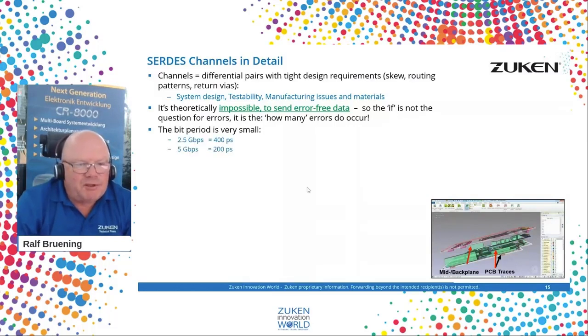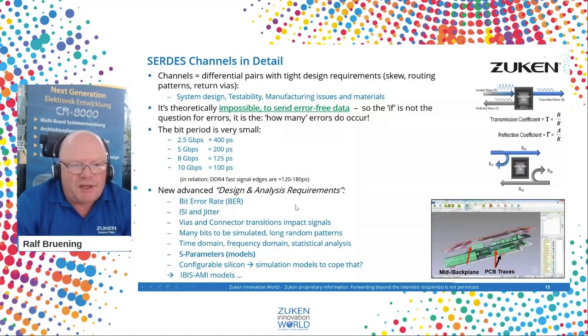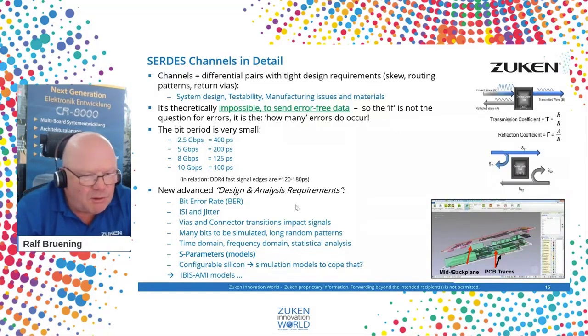The bit periods are pretty small. So depending on the data rates, we have very tiny bit periods, even faster than fast double data rate memories. As mentioned, we have the S parameters, and we have different kinds of problems with bit error rates. We have intersymbol interference. We have the different jitter aspects, crosstalk jitter, power ground noise. We have the impact of the vias in the signal path, of the conductor transitions.